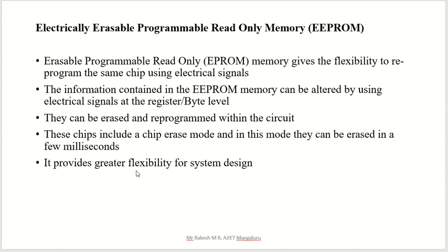It provides greater flexibility for system design. Flexibility is there because we can erase that by using electrical signal. If you are using chip erase mode, then we can erase that in a few milliseconds. That's why it is more flexible compared to the previous one.